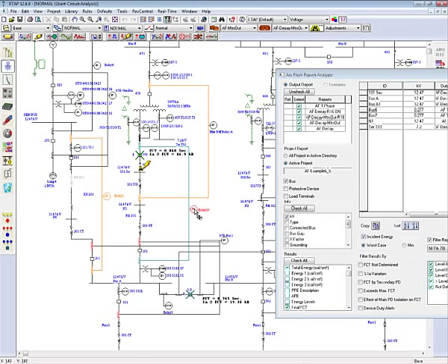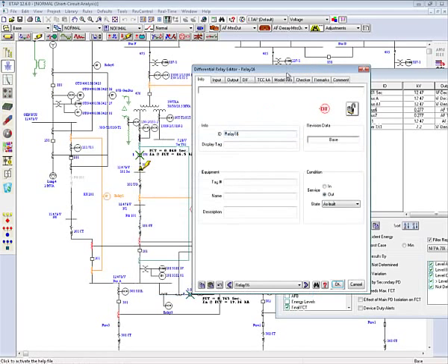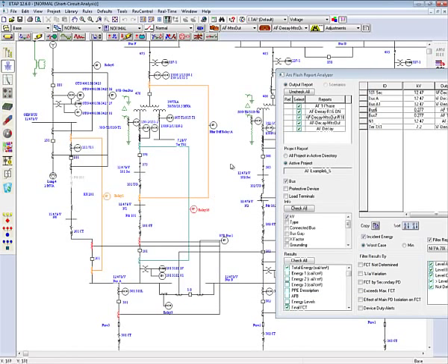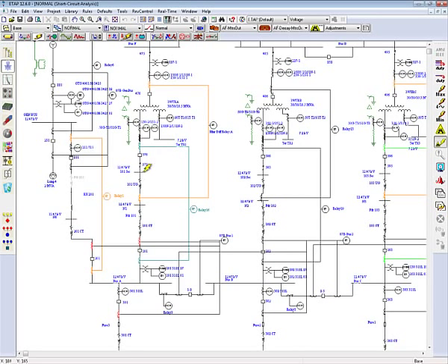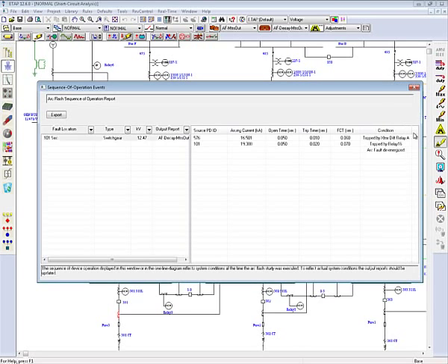So I'm going to double click it, and I notice right away in my info page that my condition is set to out of service. So if I were to put this back into service, I should expect my differential zone operating. And as you can see, the differential relay 16 zone is now de-energizing this fault well below 100 milliseconds, and you can see that change in incident energy. And of course, by launching the ArcFlash viewer, you can also see this.